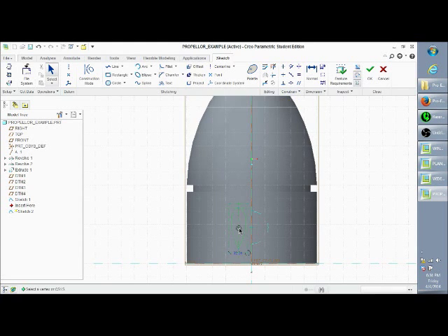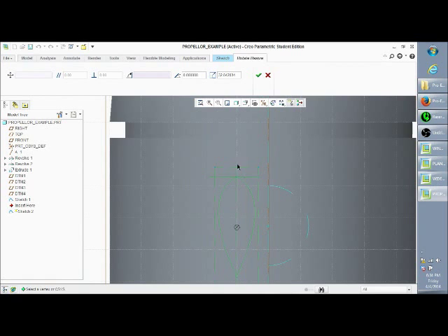So I'm just going to go over and click over here. You can zoom in, and you already see that it brought my shape in. Where this X in a circle is, that's your center for your sketch plane. So we actually want to align this with the center of this circle over here. So what you want to do is left click it, and then just drag it over, and then it'll want to lock onto your circle. So go ahead and do that.